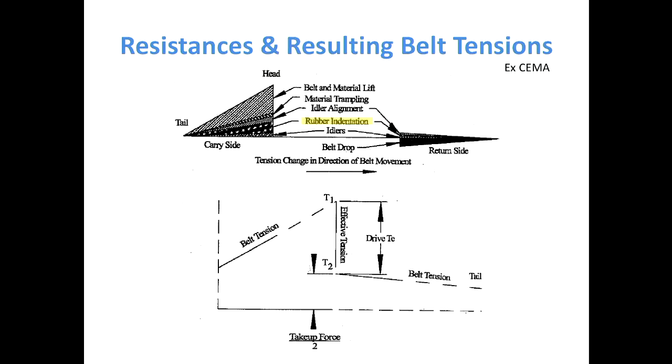But that's just in that way. When the belt's going along, it also flattens out just a little bit, but then gets squashed. Flattens out, gets squashed. So there's a lot of movement, lots of resistance. And I don't think we're going to have time to get to pipe conveyors or tube conveyors, but people actually make conveyors like that. Instead of 3 idler rollers, they have to have 6. And so what happens is you're tightening up, the tube's lifting off, tightening up, and the power on a tube conveyor is twice the power on a conveyor like that. And so that can be quite interesting.